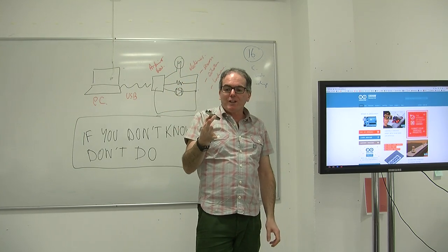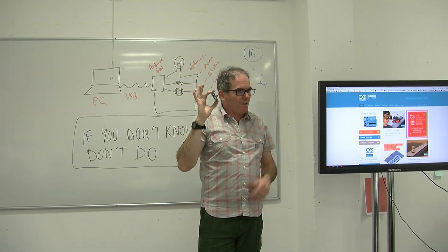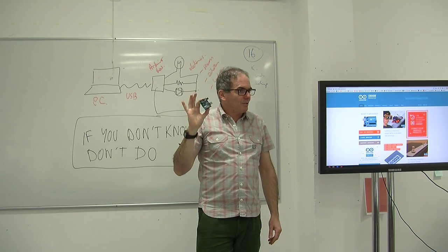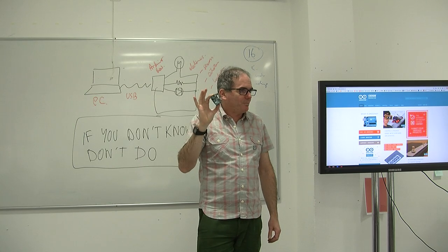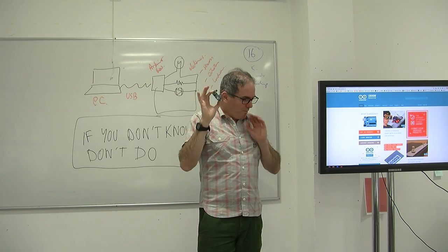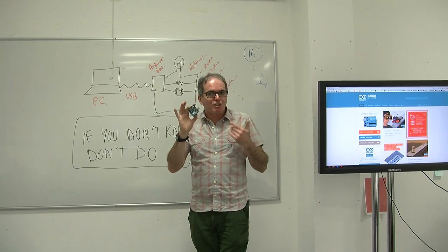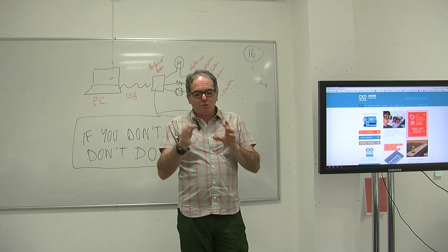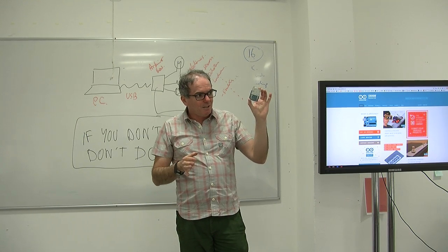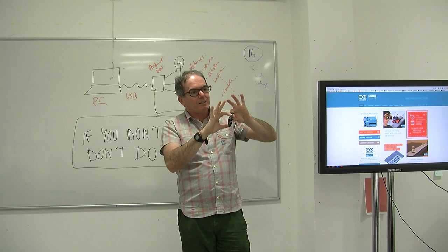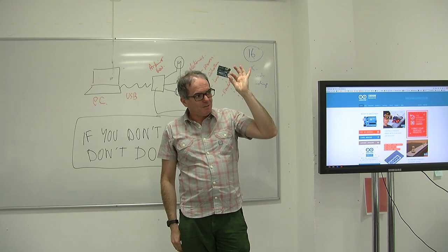Because if you touch some of the components with your fingers, you may create static and be statically charged, and there may be a static discharge on the component, and you might damage the board. So you hold it like this, not like that, always on the edge.